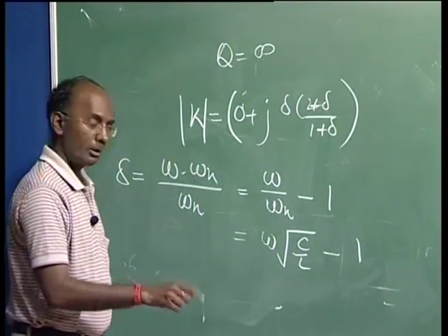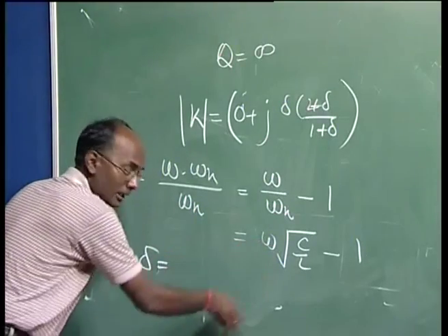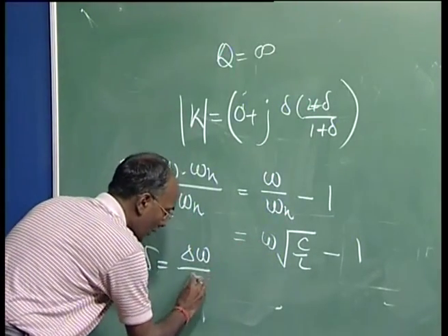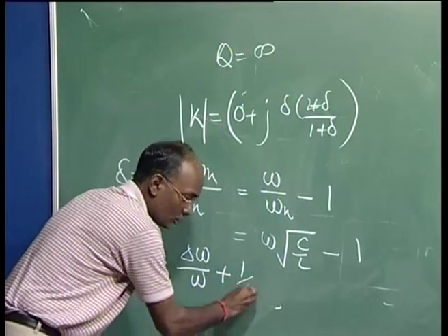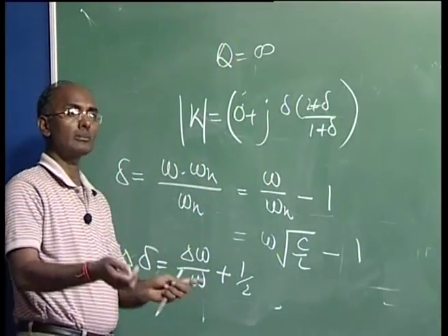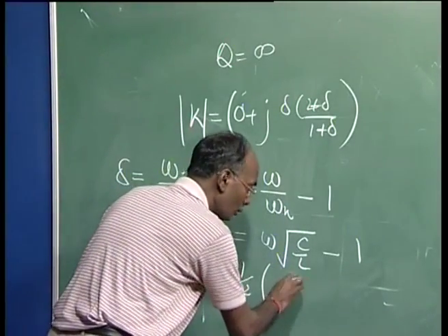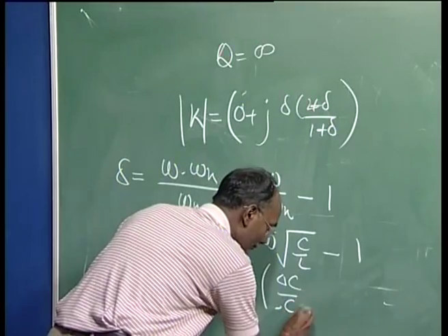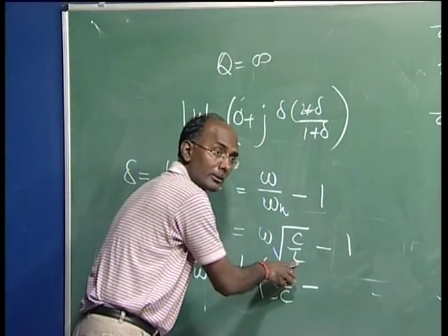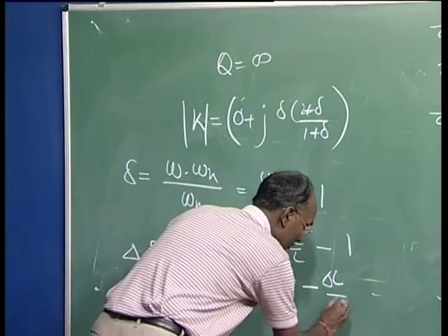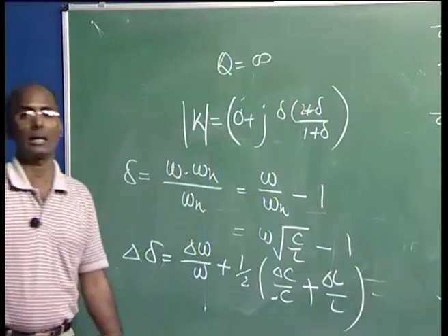So we can write the change in frequency, that is change in omega by omega, plus this under root 2, so then it will be 1/2. If it is a square term, twice is coming and then divided by 2, so here del C upon C. Here the term is coming negative if you are doing the partial differentiation, then it is L upon C, but always the error we take as positive rather than negative.